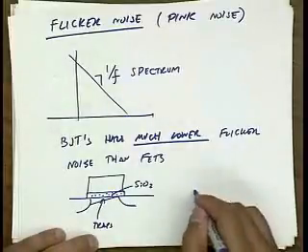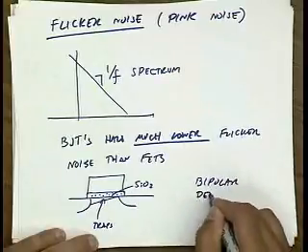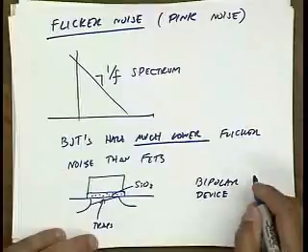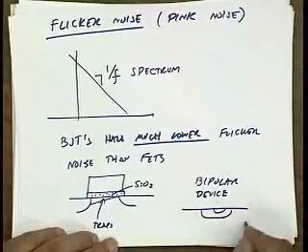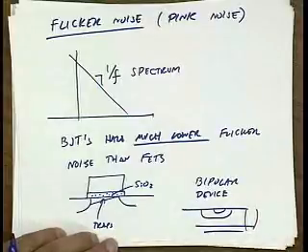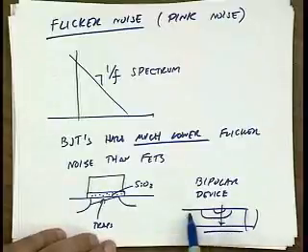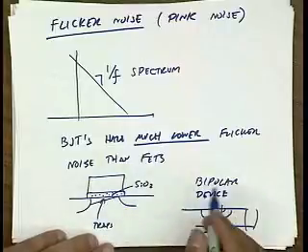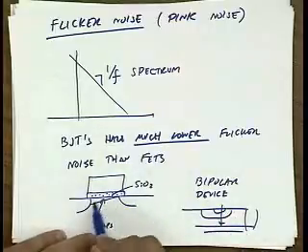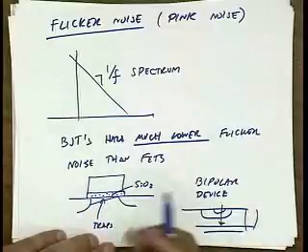On a bipolar device, though, currents flow in the bulk of the device, right? So here's a quick sketch of a bipolar. The bipolar action occurs under the surface. So the surface is where you don't want to be. The surface has these so-called dangling bonds, incomplete bonds made at this interface, which are the trap sites.